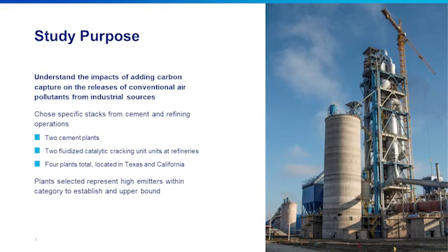So emissions can also go down. In order to use this carbon capture system, you have to take out some of these air pollutants because they interfere with the chemistry of the unit. Dr. Wilcox mentioned that NOx and SO2 are strong acids. Those form heat-stable salts with the amine. And so if you want to have this run, then you have to clean up some of these emissions beforehand.